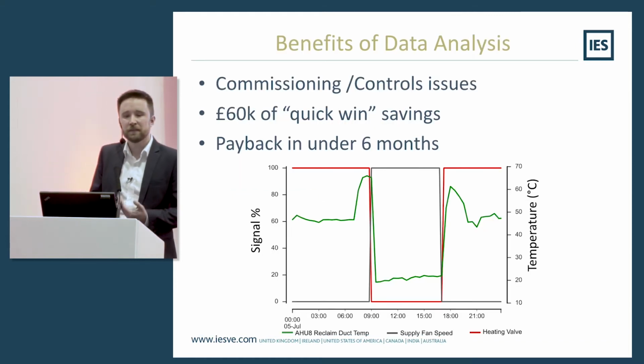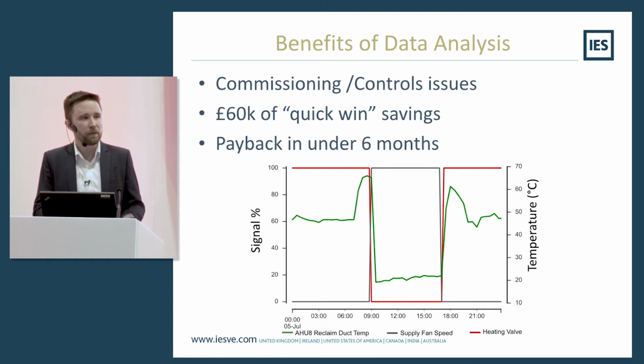But even by itself, data analysis is worthwhile in modern commercial buildings. Often you can find very quick wins of savings to be made that arise from commissioning and controls issues that arise from the sort of performance gap I touched on earlier. So when time to do commissioning is squeezed or commissioning budgets are squeezed, often systems in new buildings aren't performing as they were intended by the designer. By looking at this data with modern analytical tools, you can quickly find savings that can be made just by small tweaks, changing set points, run hours, and also you might find bigger opportunities for savings through capital investment.